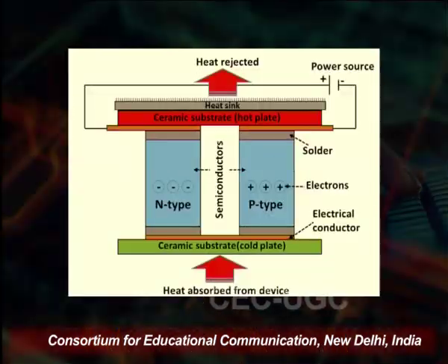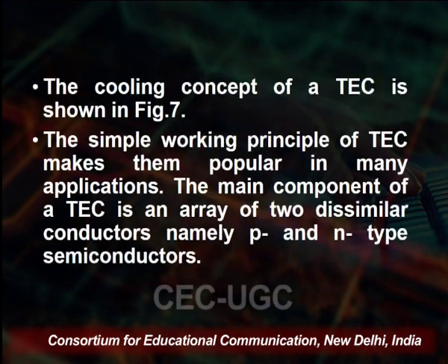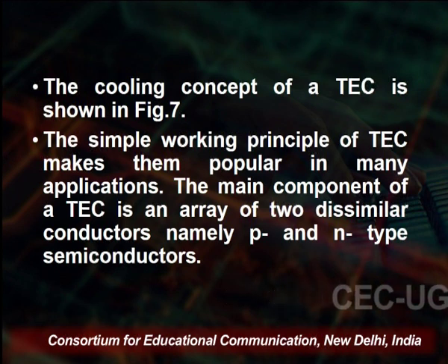You see on the screen here a thermoelectric setup in which the heat is absorbed and the heat is ejected. In between, we have the electrical conductor as well as the soldering, and N type and P type, as we are using the semiconductor. So we have an N type and P type system, with one side absorbing and the other side rejecting the heat. The cooling concept of the TEC is shown in the figure.